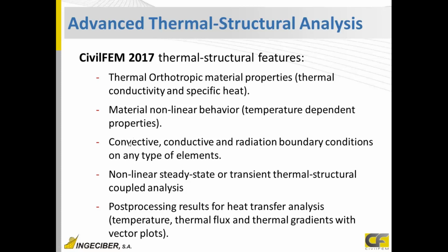The thermal boundary conditions we can apply are convective, conductive, and radiation boundary conditions on any type of elements. And as I said, nonlinear steady state or transient. Thermal structural analysis coupled, or just thermal or just structural, we can solve any, and plot the results, plotting, listing, with vectors, any type of value.